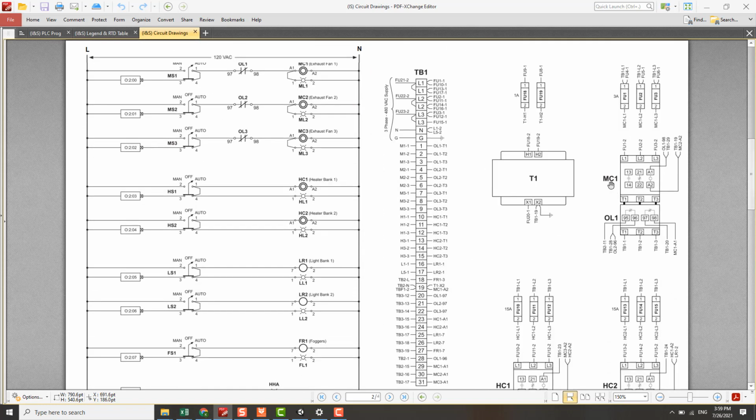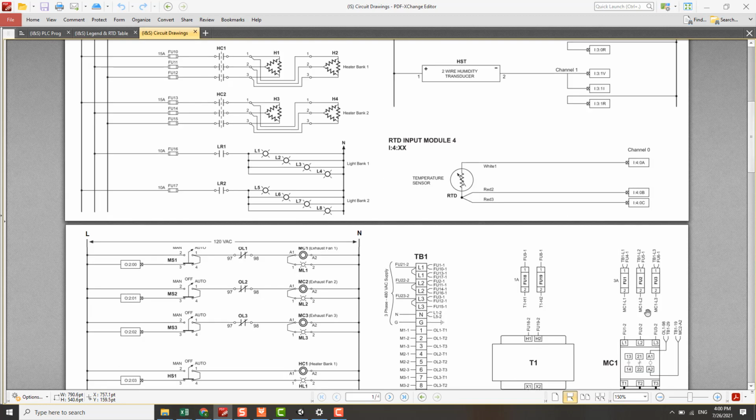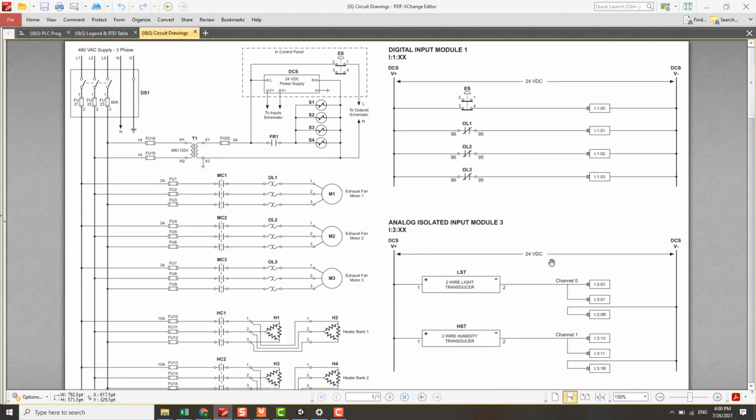Okay, this is the motor contactor 1. This is the overload relay 1. So it has 95, 96, 97, 98. These both are the auxiliary switches attached to the overload relay. Pin 97, 98 here is connected to the PLC output circuit, while pin 95, 96 of the overload relay 1 is actually connected to the PLC input circuit, which is using DC voltage. So they are two totally different circuits. Don't misunderstand. So we need to check this one.